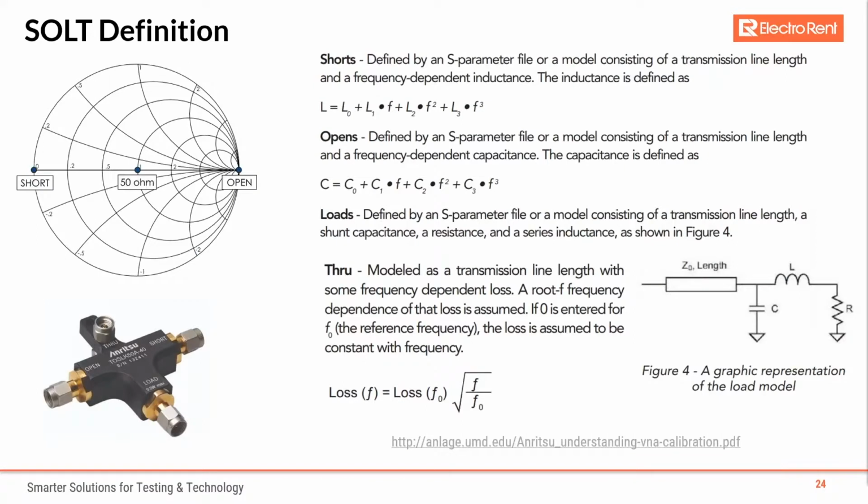So what is the SOLT definition all about, and what's it for? Well, you want to calibrate out your shorts, defined in the S parameter file, in regards to inductance. Calibrating out opens will help calibrate out the transmission lines for capacitance. Cal kits are needed in order to remove any extra frequency response reflection from a given line that has been added to the VNA. This helps move the measurement plane and keep it accurate. In the case of 50 ohm device systems, you want your measurement plane to be as close to 50 ohms, as here in the Smith chart example, as possible.